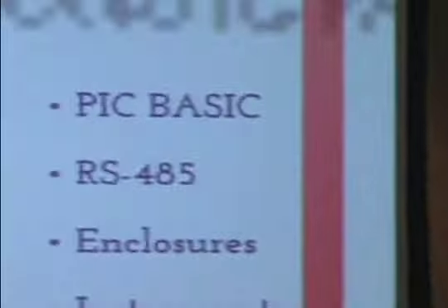The next challenge that we had was RS-485. Since we have 3 different devices on the same bus, we can't use RS-232 because RS-232 is a one-to-one protocol. So we use the RS-485 protocol. RS-485 is just a hardware protocol which says that you have a bus between your instruments, the devices, and the bus has 3 lines, one ground and 2 lines A and B, which are the inverse of each other. If A is 1, B is 0, and if B is 1, A is 0.